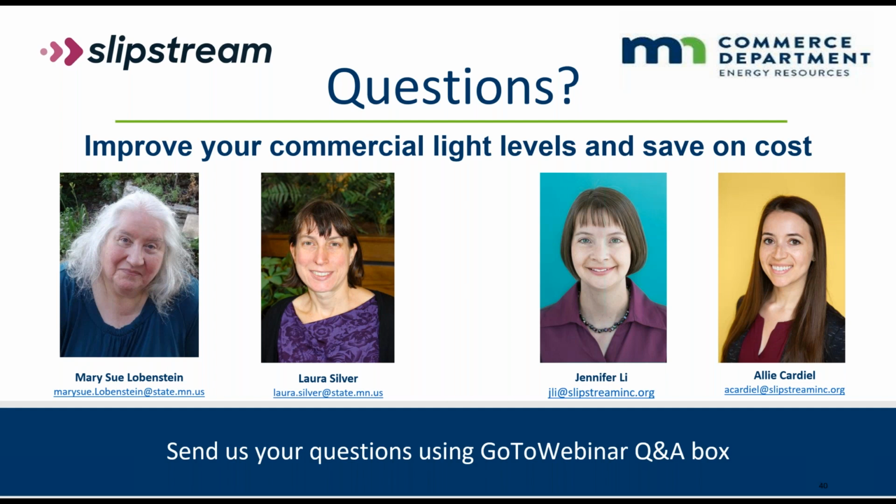Okay, it does certainly help to understand for any space type the specific types of tasks that you're expecting to occur in those spaces. IES recommendations are based on the actual activity occurring in a space. So if we think about a classroom or a conference room, when we talk about appropriate light levels, a reasonable assumption, say for a classroom, might be that you're completing more paper-based tasks that involve reading and writing.